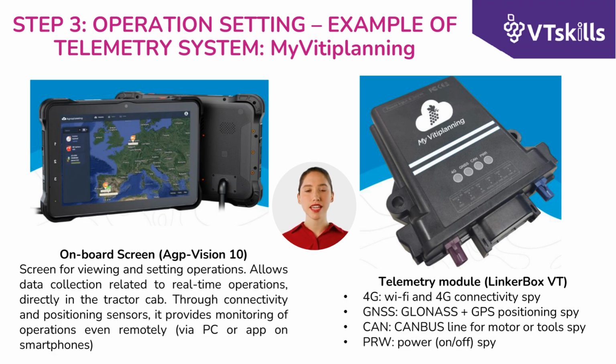In the most advanced systems, it is also possible to support sending safety alerts to the operator when critical thresholds are exceeded. For example, in areas with a high gradient, maximum thresholds can be set for lateral and longitudinal slopes that can be tackled to ensure the stability of the worksite, which are measured by accelerometers in the tractor and/or sprayer machine. When exceeded, a message is sent to the operator, who intervenes by returning to a safe condition.